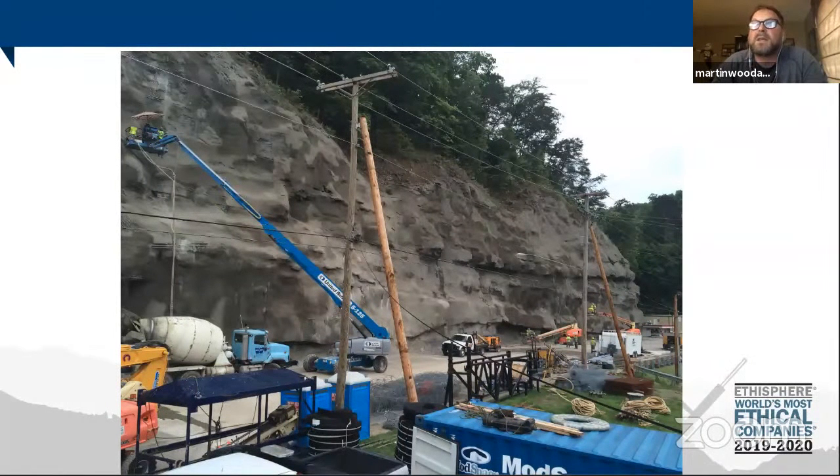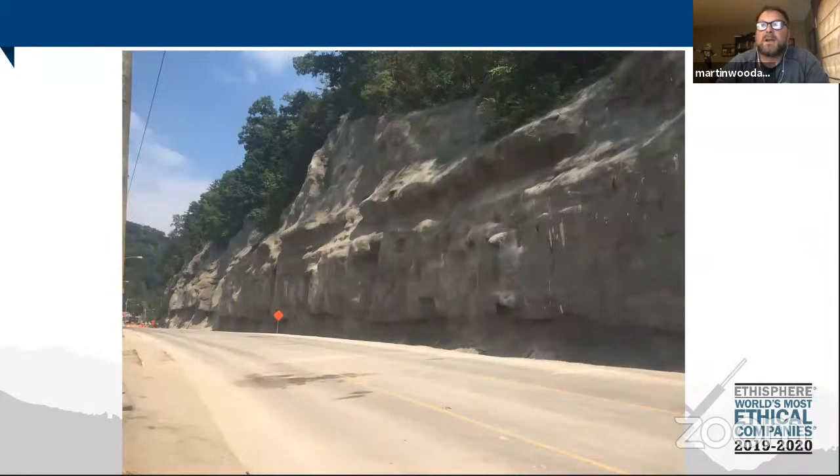So when you start looking at these pictures, the shotcrete is covering all of these slopes. We have horizontal drains. We have these vertical drain units. And we're starting to deal with all of these erosional issues. So you're getting rid of those types of features. And this particular area was around 2,000 lineal feet long. The slopes ranged from about 40 foot tall here to the top of the peaks at about 45 feet. And this is all a shotcrete armoring system in downtown Pikeville, Kentucky.